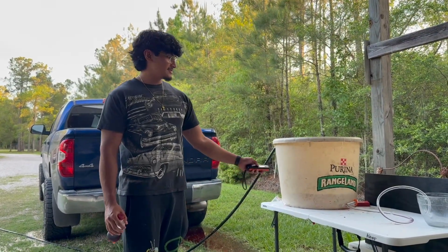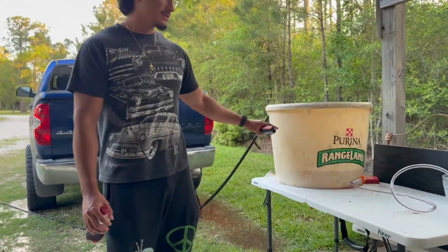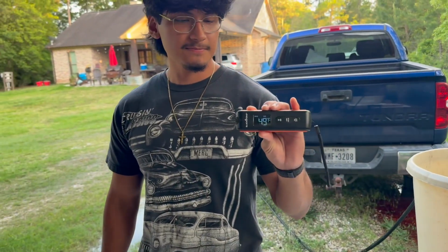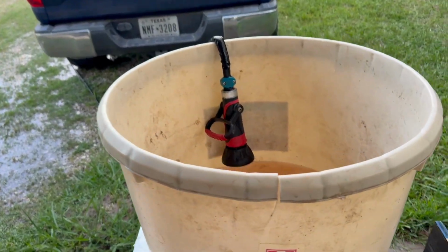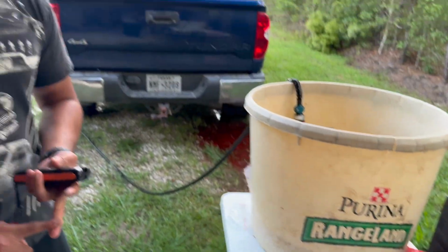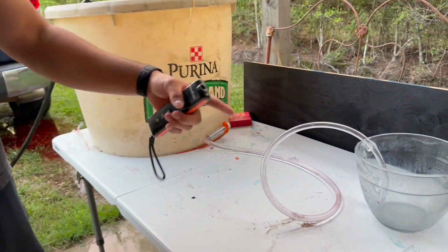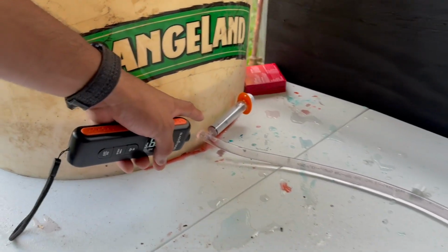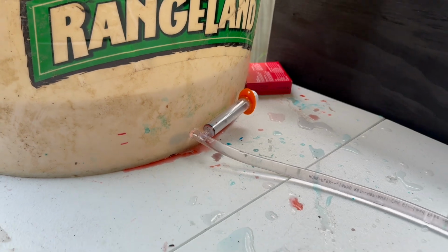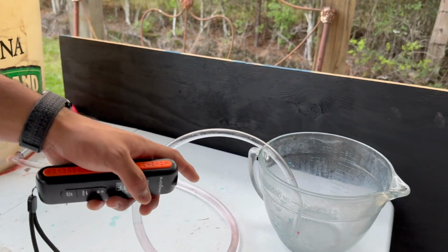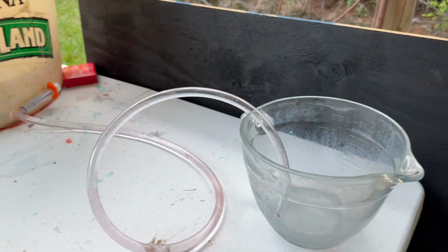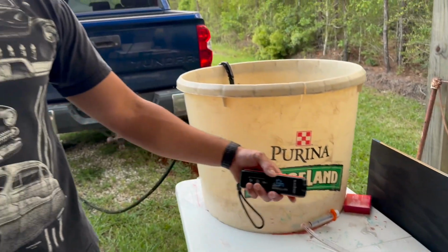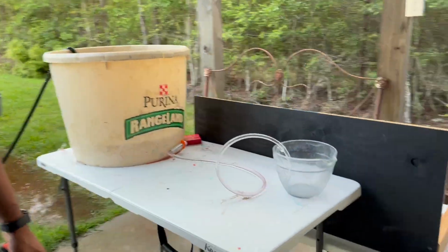Alright, this is the experimental setup that we have. So we have the water container where we are going to be filling up the water. And we have the thermometer to see how cold the water is, so we can find the viscosity and everything else we need. We have the tube right here, which is 3/8 inner diameter. And right here is where we're going to be injecting the dye to be able to see the flow of the water. And right here we have the measuring device to calculate the flow rate and then find the velocity. And we have the background to make it more clear and visible.